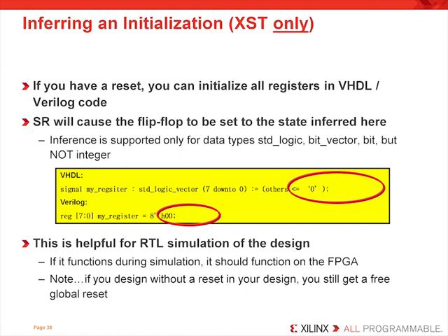For example, if you do not do this and you have a counter, you will have X's counting plus 1, and all you will have is what's called an X counter. You will not have anything more than that, but if you use this with a counter or anything else, it will start with a known value. This is definitely a coding style you should be using, whether you're doing a set or reset.